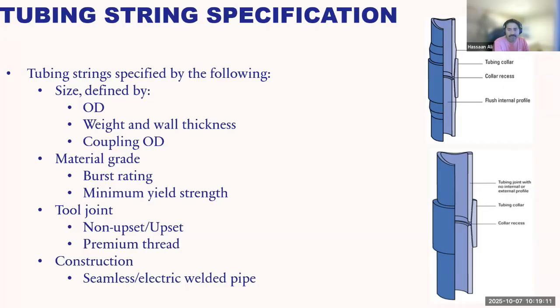Therefore, proper selection, design, and installation of the tubing is very important for any completion system. The size and dimensions of the tubing must be sized to enable efficient production. The grade of the tubing should be selected to prevent failures from the tensile forces, internal and external pressures, and the corrosive nature of the wellbore fluid.